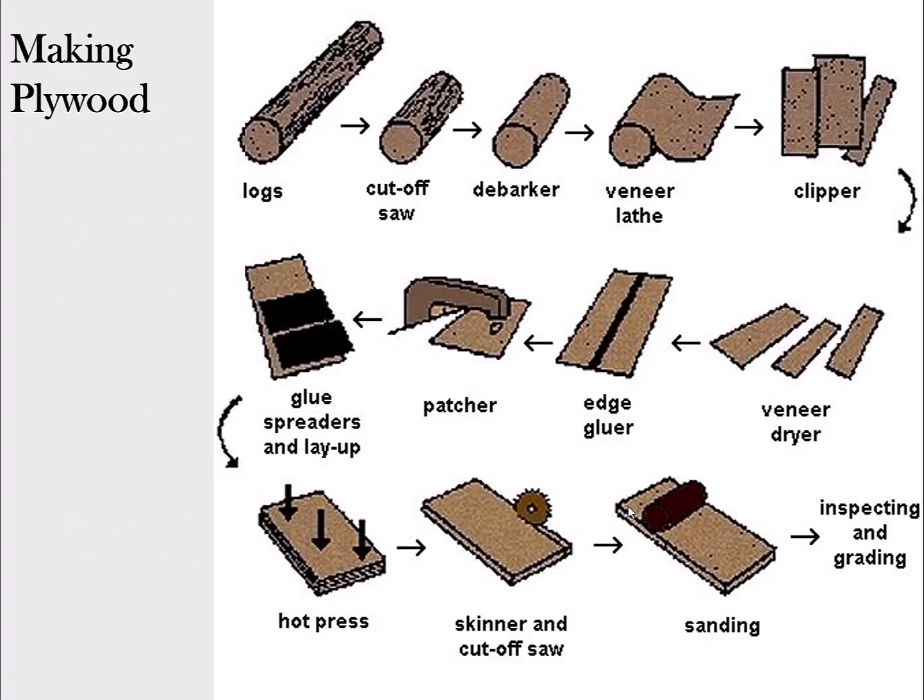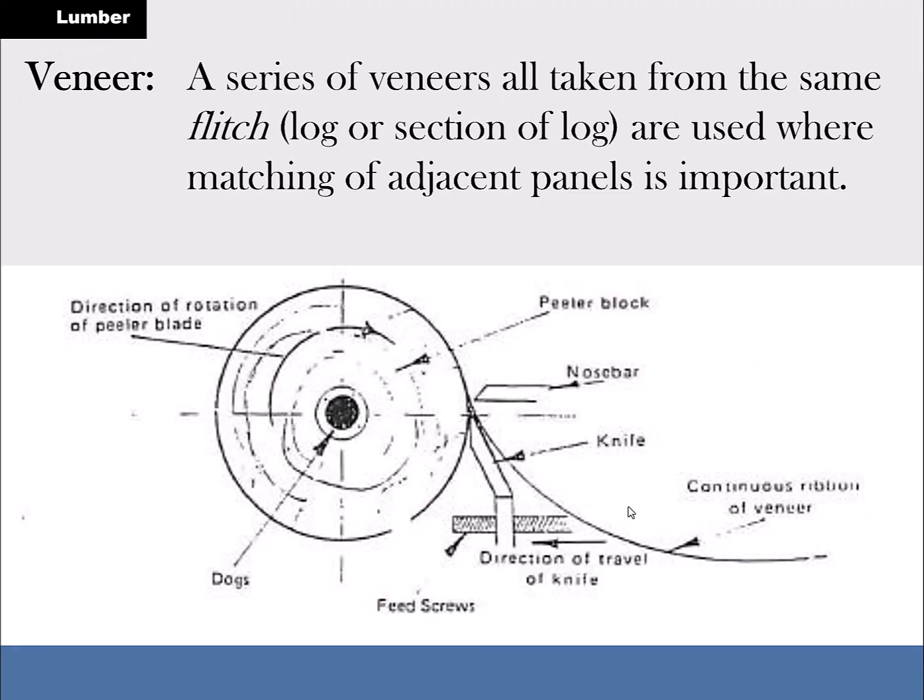Now, making of plywood, well, they'll take logs and they'll literally have a knife edge on the end, and they kind of peel the log like a roll of toilet paper. But they've got to do it with some very elaborate chisels that are pushing and vibrating to peel the wood away from the log itself. And that's how most veneers are made. And then they can glue them all together as pieces. So yeah, kind of like unrolling toilet paper. But of course, what they really do is have a knife edge and they're torquing that load of the log around the corner.